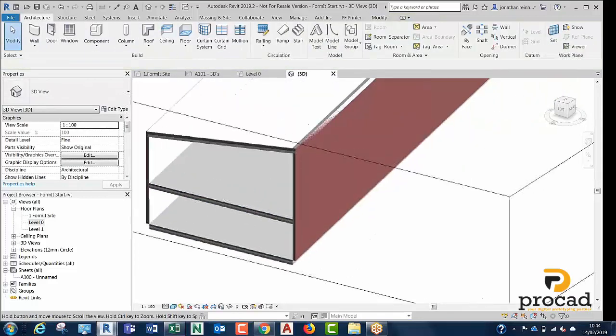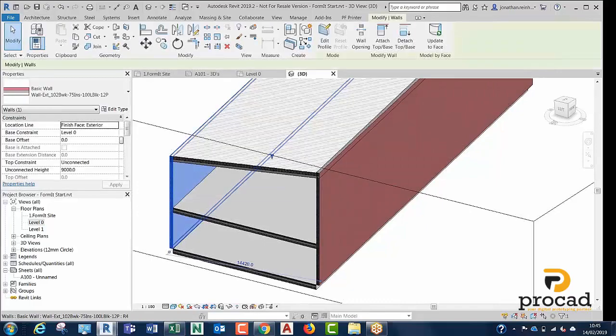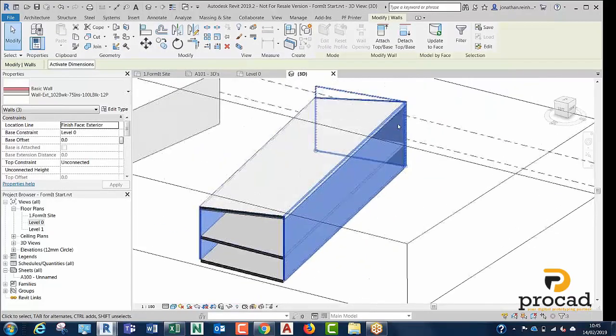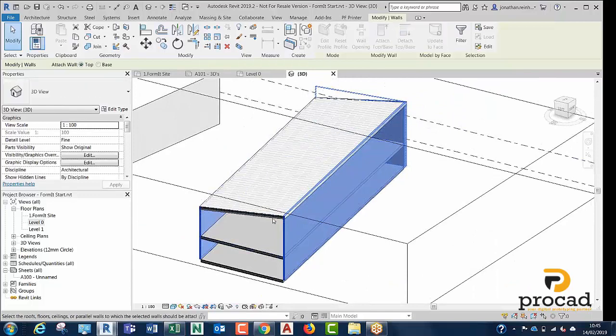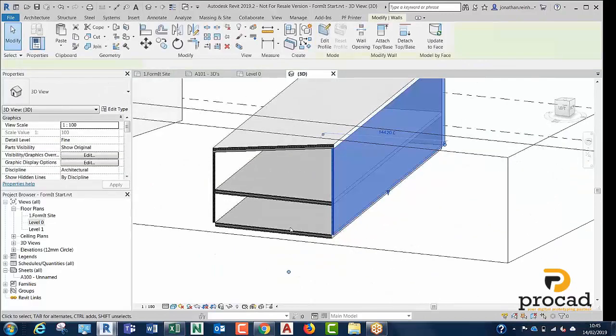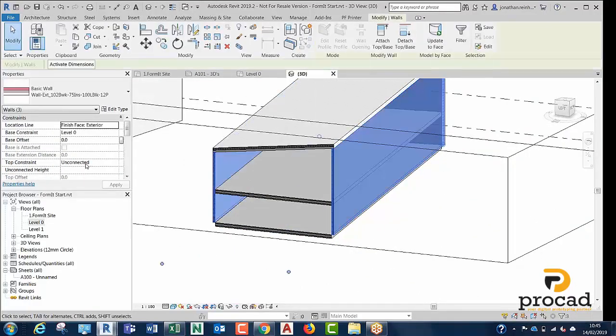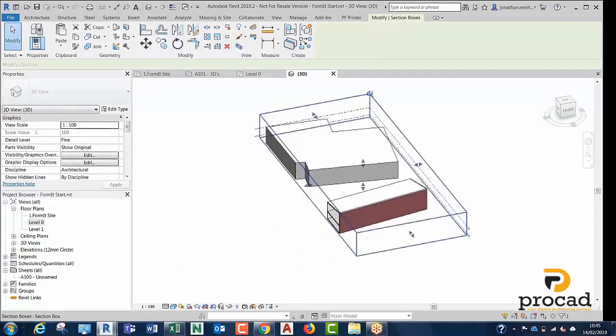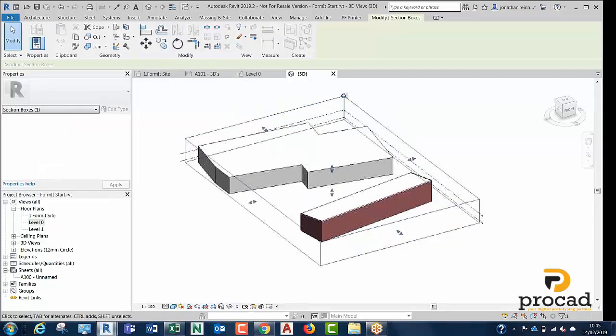You can keep this in the background if you want, and then I'm going to attach all of my walls to my roof. Just going to select the walls using the tab key. It'll take all 4 of them in. Just going to tap that into there. Attach elements, and that's connected all my elements to my roof. And then for my other walls, I'm going to put a base offset onto those as well, just so they come below the ground. Minus 350. Hit apply, and you can see within a matter of minutes you've got almost a building with wall construction, if that's what you want.